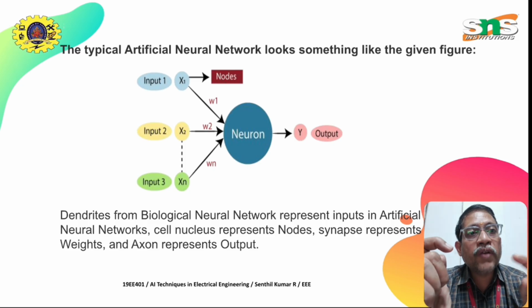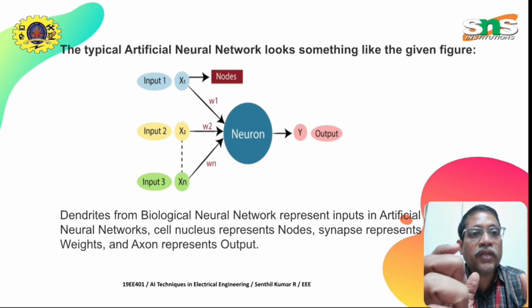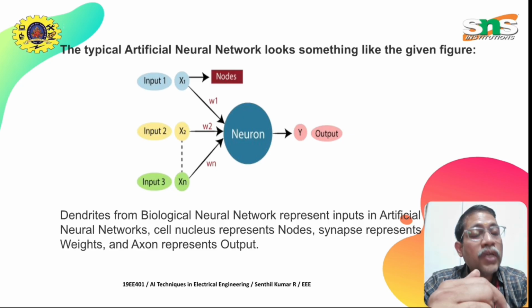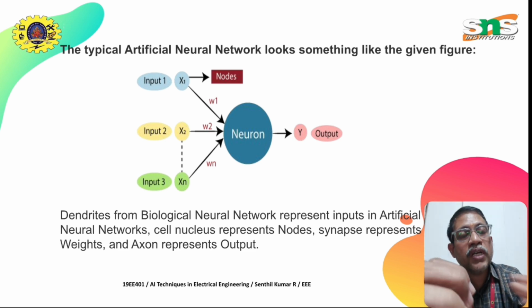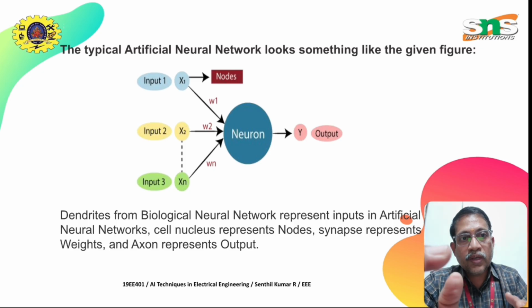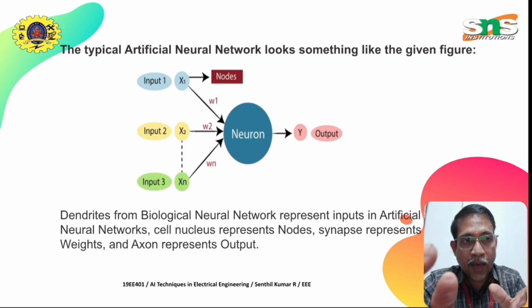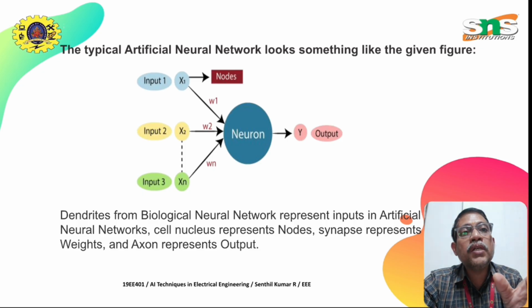In order to make the filament glow, nearly 1000 volts has to be generated, and this 1000 volts is generated with the help of a choke and starter assembly. The choke generates 1000 volts, and it is released with the help of a starter, such that there is an electrical flicker between the two elements of the fluorescent lamp. If the 1000 volts is reached, then the lamp glows. The threshold value is 1000 volts.